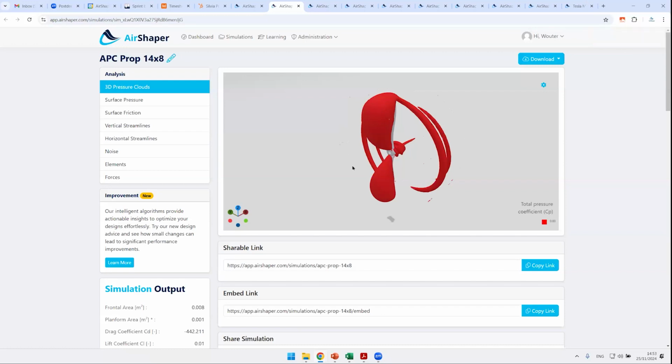And you can always question yourself, is it by accident that I'm within 5%, or is it really that close? For that reason, you should usually, especially when you're optimizing your method, which you will then repeatedly use, do a mesh sensitivity study, which is to run a simulation, let's say 1 million cells, 10 million cells, 100 million cells, 500 million cells, and then plot curves through those results, to plot your drag, to plot your lift in function of the number of cells.